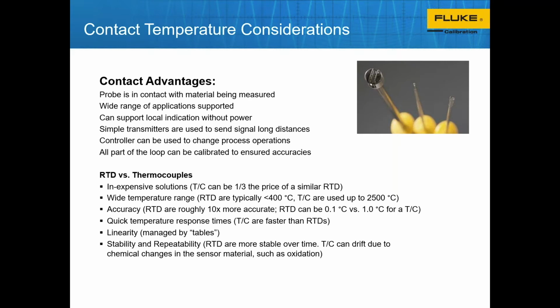Being able to measure all of these different parts is critical, and that's really what this entire presentation is going to be about. Just a quick comment between RTDs and thermocouples. I mentioned them earlier as potentially the most popular versions of temperature probes out in industry. If you're not familiar with the differences, thermocouples themselves are fairly inexpensive. They're made with two dissimilar metals that are fused together, and those dissimilar metals will create a standard millivolt output based on the temperature of that junction.